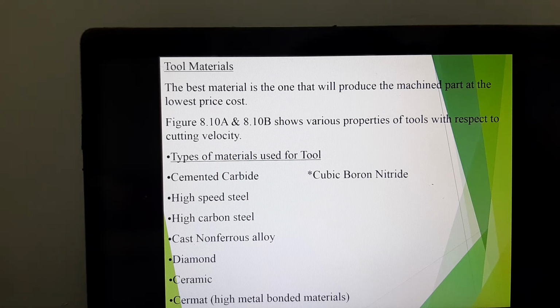If there is a chemical reaction, initially your material is aluminum, and after the cutting process at the region of cut, you will find that the material has transformed to aluminum oxide. Oh, that is a disaster, because that is going to change the characteristics of your material. You want an inert cutting tool material, and both cemented carbide and high-speed steel possess those characteristics.